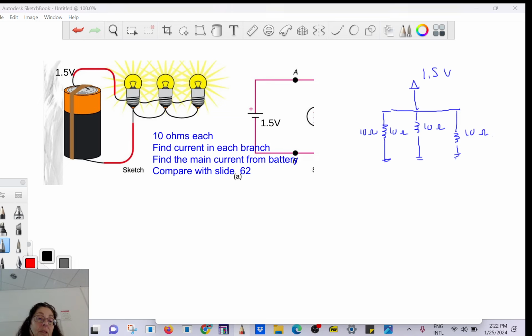So what do you think the voltage drop is across here? By how much is it going to fall? So it starts from here. What's the height here? 1.5. This is the ground. So all of them will fall by 1.5, right? If they are connected in parallel, they all will be provided with 1.5. That's what I showed you with the simulation. So 1.5. Now, can you find for me the current? So I'm going to have the current I1, current I2, and the current I3.